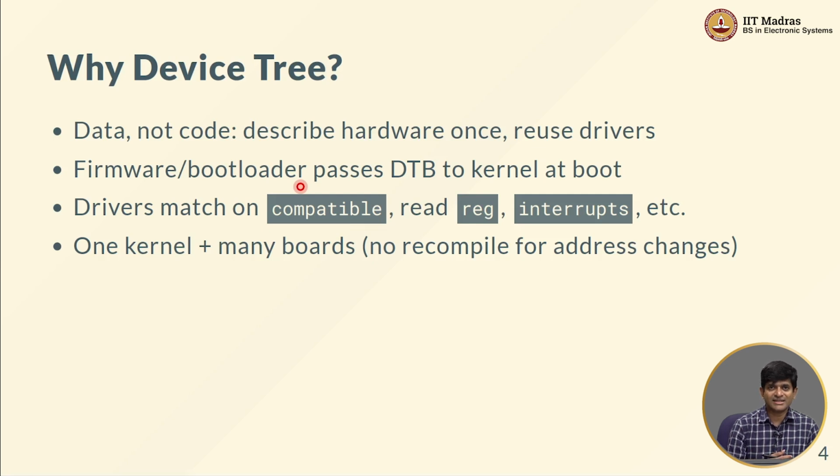Now the interesting thing is, if you think about how a Raspberry Pi boots, the operating system for the Raspberry Pi is not actually flashed into a very specific location in memory. It comes from the SD card. Now how do I read from an SD card? That itself is a piece of hardware which requires its own driver. So it looks like a circular argument, and that's literally what the idea of bootstrapping or booting is.